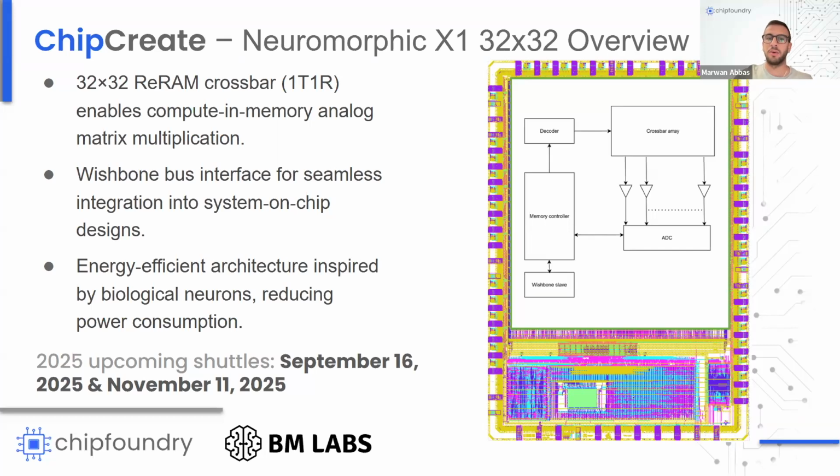So the question is, how can they refill the FIFO? They can just keep giving the read command and they can just keep filling the read FIFO. And for the write FIFO, they can just keep looping the write command because, as I mentioned, this IP is like EEPROM. So it has a buffer, which is the FIFO.